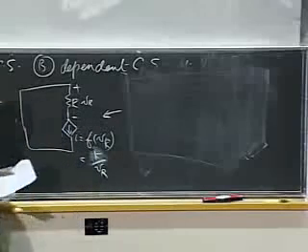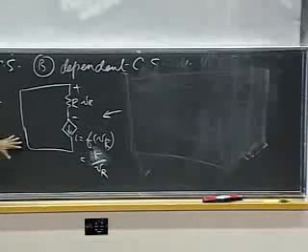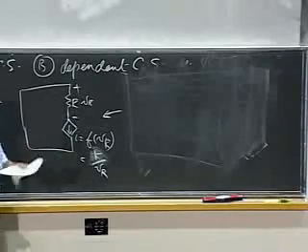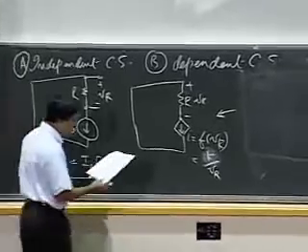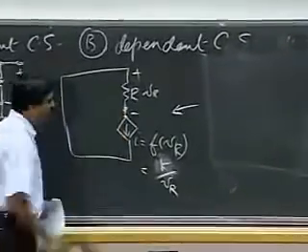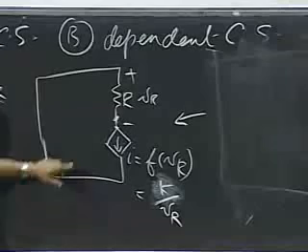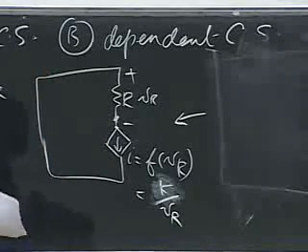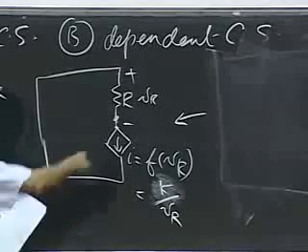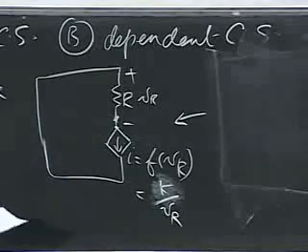Okay, so let's go ahead and analyze this little circuit here and look at what this might give us. Our goal, as before, is to find out the value VR. So in this case, let's apply the node method to this node, and sum the currents going into that node to be 0.